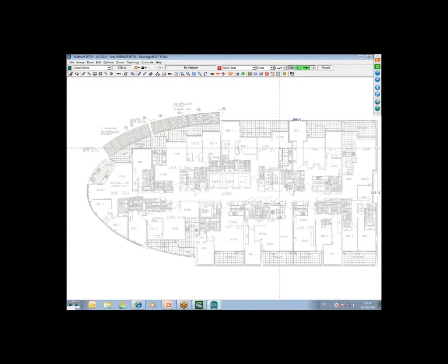So sometimes that can be quite difficult to do when you're dealing with an image file that you receive. The image file itself may not contain any visible dims on the lines. There is no easy way around that. You really have to, firstly, before you can begin using that drawing file, determine the length of 2 lines, one horizontal and one vertical, and then the system will calibrate.